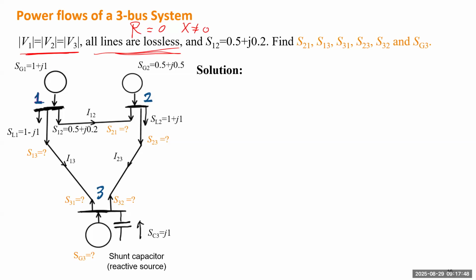So we want to solve the line flow of every single line. So you see here, we gave some information already. We usually draw a bar like that one, and we call it a bus. A bus means just a substation. A substation can be connected to many transmission lines and many devices. In a graph, it can be treated as a node, but in power systems, we call it a bus. And so bus number 1 and number 2 will be power plants, because they have generators connected to the bus, and those two generators will generate complex power.